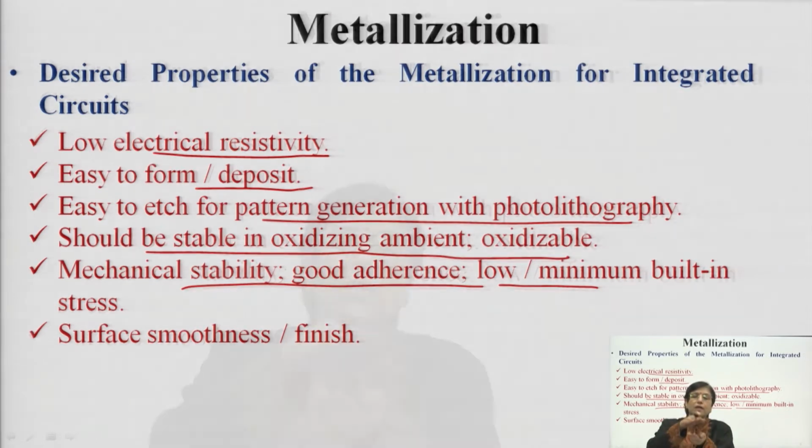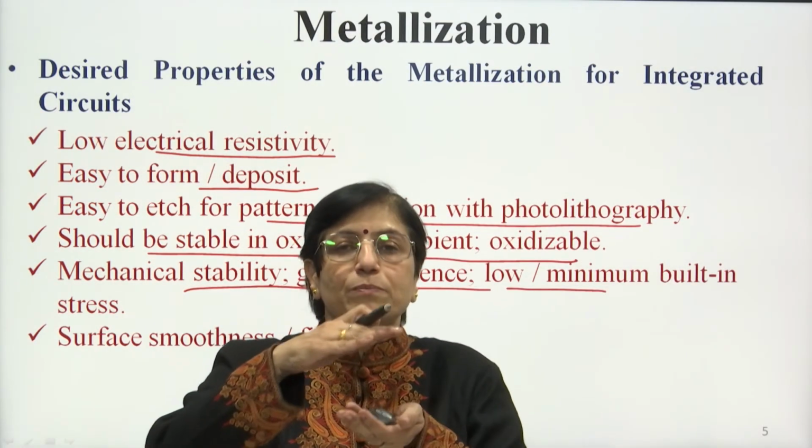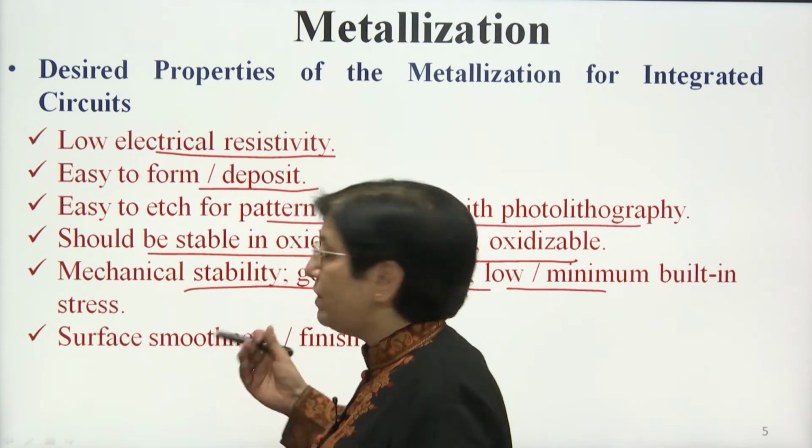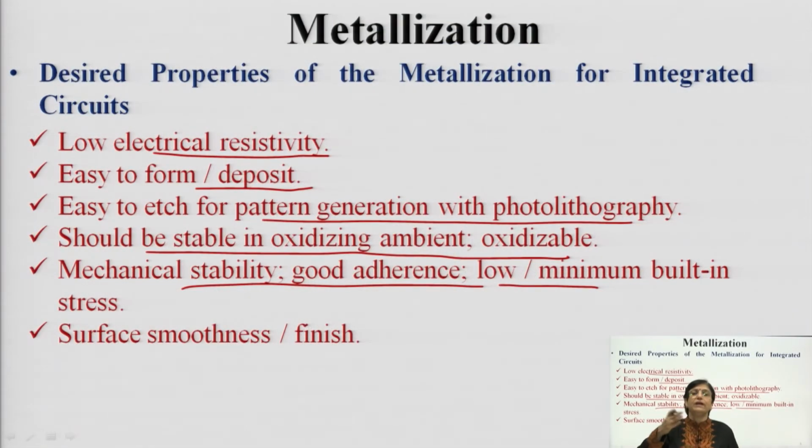Any stress, any mismatch in the layering or any improper sticking may result in the film getting torn off, or wear and tear can result, and that may cause discontinuity problems within the interconnects, and you do not want that to happen. Therefore, it should have good adherence, it should get properly stuck up, should adhere, and should establish proper contact without any loss of connectivity.